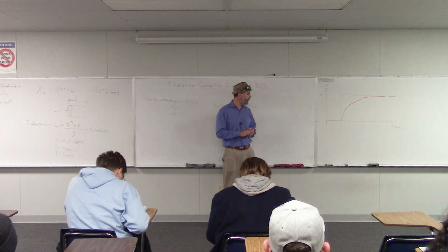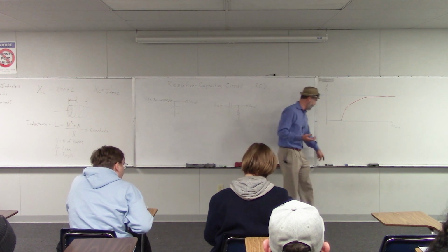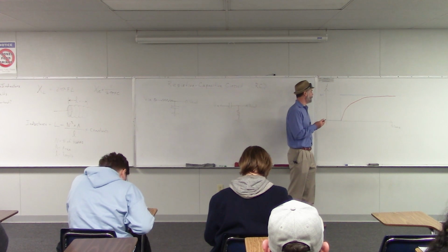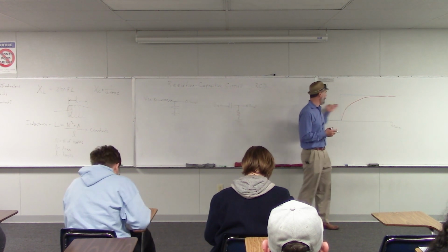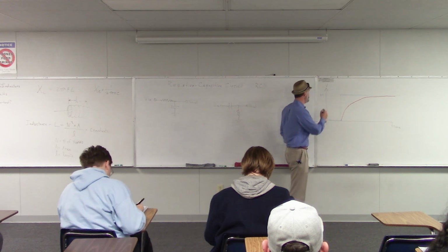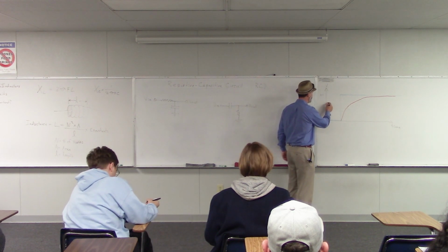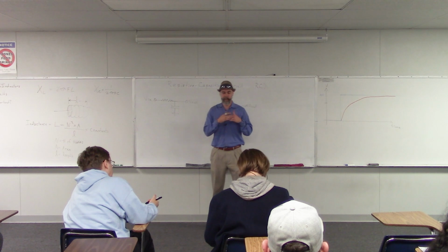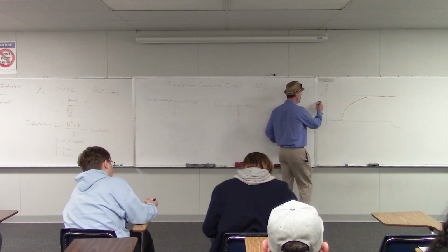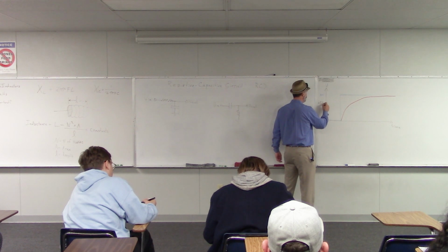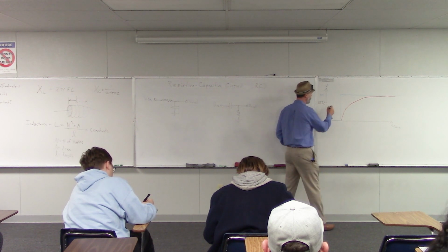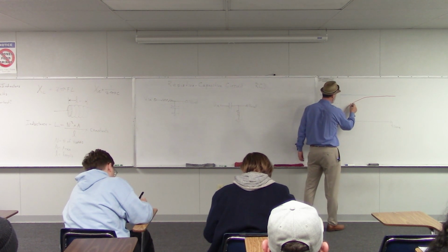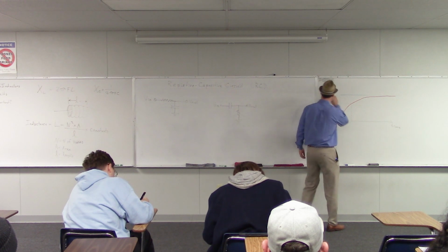Well, what people have decided over the years is that, okay, it's never going to fully charge, but we can pick some value and measure how long it takes to get to that particular charge value. So we can take a value of 63.2%, and we can measure how long it takes for the capacitor to charge up to 63.2% of the input voltage.